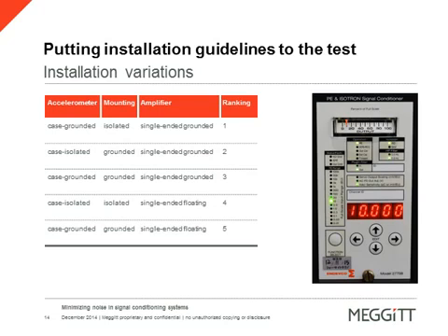Now, as far as the installation variations, we have a small table here to identify the variations. We went from a case grounded accelerometer with an isolated mounting stud into the single-ended grounded amplifier, and we took that through several variations to our case grounded accelerometer with a grounded mount and a single-ended floating amplifier, which is item 5. Depicted to the right is the face of the single-ended conditioner 2775B, and also in that picture you can see where we have some options to do isolated or grounded on the input line.